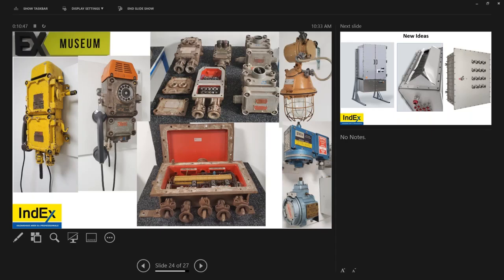Thought you might explain pressure piling. Okay, pressure piling is an internal explosion. When it happens, the pressure wave bounces off a solid surface and bounces back at even greater pressure. As it bounces back and forth inside, it has more energy, and it will crack the EXD enclosure if it didn't have a flame path. The flame path allows the release of that explosion in a controlled manner.